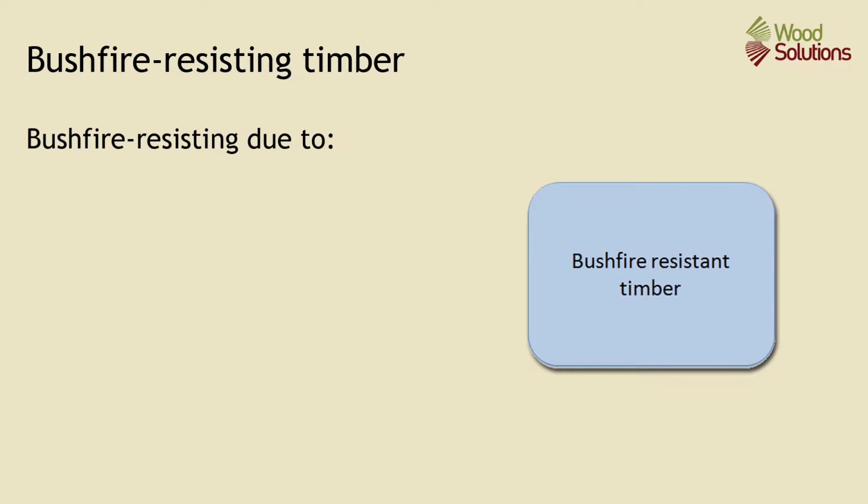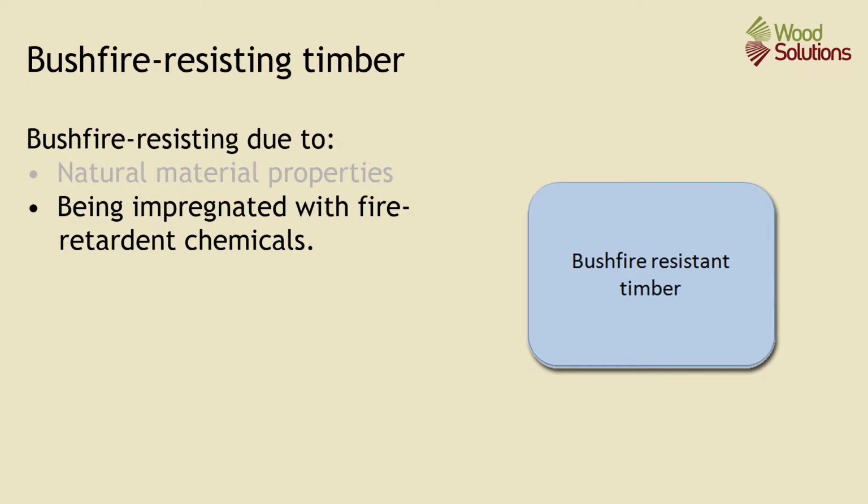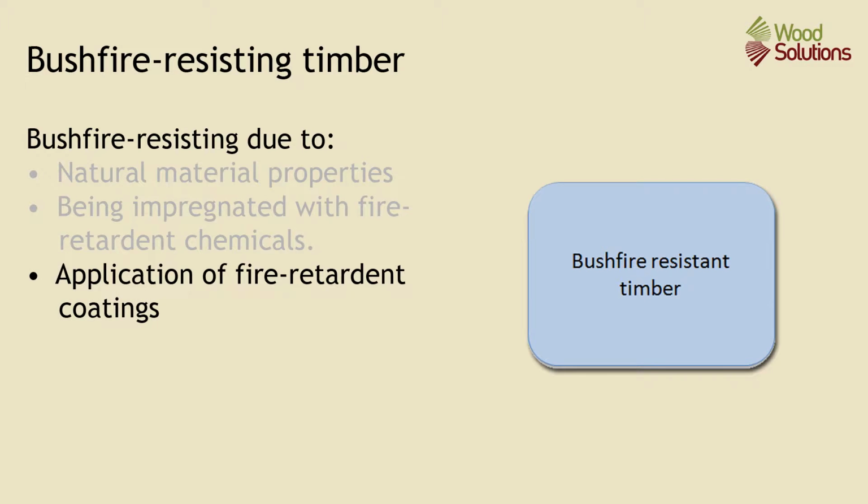Bushfire-resisting timber may be bushfire-resisting due to either the natural properties of the material or to impregnation of the timber with fire-retardant chemicals or the application of some fire-retardant coatings. Fire-retardant treatments and coatings are specialist products, and test results for these products should be sought from the supplier. We will not be covering treated material in this presentation.